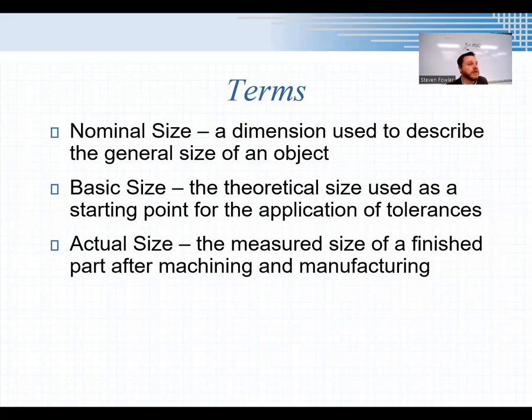So it is stable then. It's close to 2x4 at that point, and then it shrinks down. Or if it's not dried, if it's treated, they go ahead and cut it down to about the standard length that a dried plank would be. But that's your nominal size. That 2x4, it means that's nominally 2 inches by 4 inches. It's not exactly, and in fact, in lumber, because as I said, because it's treated, it shrinks. It's not 2 inches by 4 inches, but that's what we call it. It's a 2 inch by 4 inch.